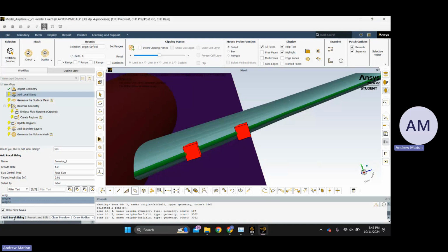When you're doing the name selections, do you do that after you've done the Boolean subtraction? Yes. You would do it in the geometry. You can select faces in the geometry modeler. There's an option where you just select faces, and let's say you want to select the whole aircraft and name all the aircraft. If you click that, you get every single face on the aircraft. Or you can name it trailing edge, wing, fuselage in there.